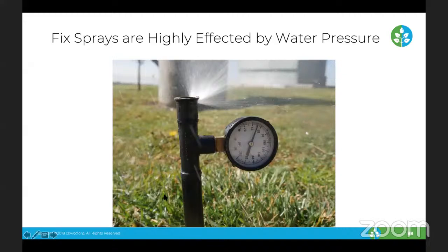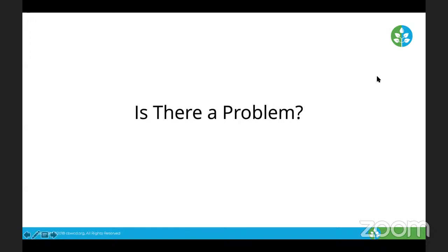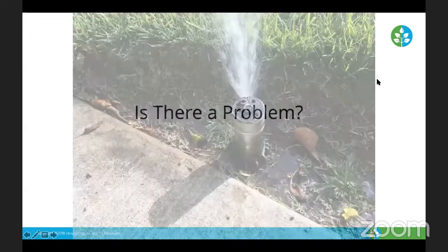So the body is pressure regulated. When the water from the system passes through that sprinkler, it is regulated to 30 PSI. There's 30 PSI and 45 PSI regulated sprinkler bodies, and those will help keep the pressure at the nozzle in the appropriate amount. So we'll see how that works over time as far as irrigation efficiency, but something to keep in the back of our minds. Pressure regulation.